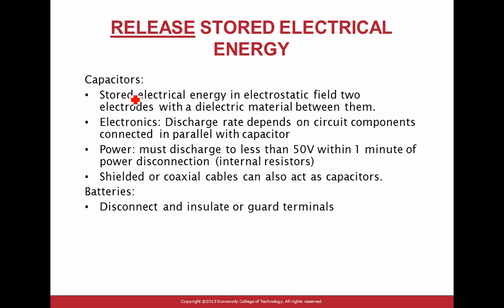Some of your equipment, guys, might have a disconnect qualified as a plug. Unplug that piece of equipment. Now you've disconnected it from the power source. A plug is a disconnect. Circuit breaker, certain equipment, in your case at the voltage level that you work, you can go to the circuit breaker, turn it off, and you put a lock on it and lock it. That's an acceptable means of locking it for smaller loads. For bigger loads, that's what you see, that big disconnect.